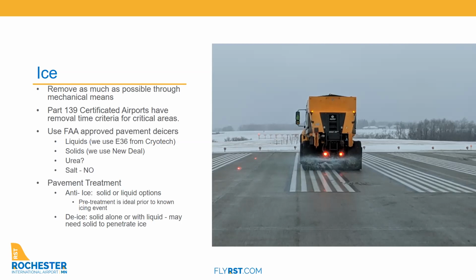Certainly at an airport of our size, our snow and ice control plan says that we have to respond to ice immediately. We can't respond to it the next day or the next morning. If it starts freezing rain at midnight, we're addressing it at that time. There are several FAA approved pavement deicers. We typically use E36 as our liquid, and then we use New Deal as a solid. Cryotech sells liquid and solid. They sell a product called MAC that's a solid, but we've found New Deal to be a little bit better.